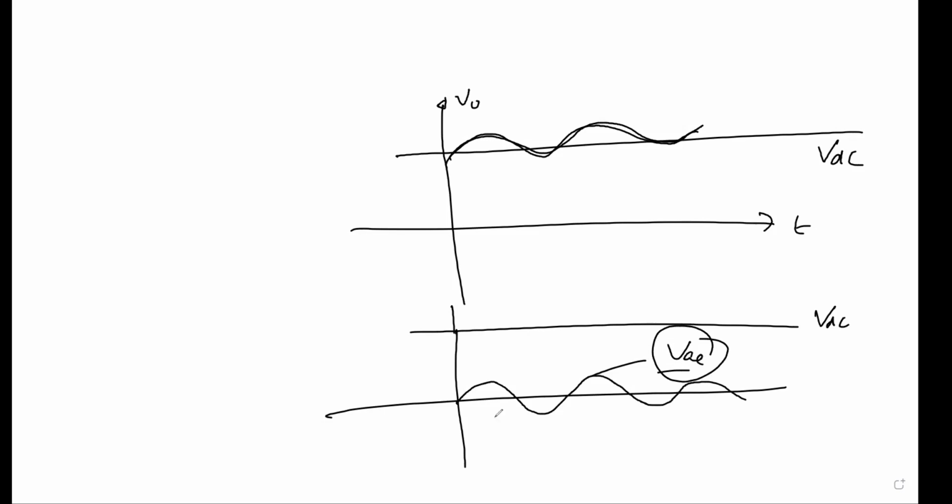You don't need to do all these things. You have to find out the peak value, then you get the equation, and then you do your integration, squaring it and averaging it, and take the root.